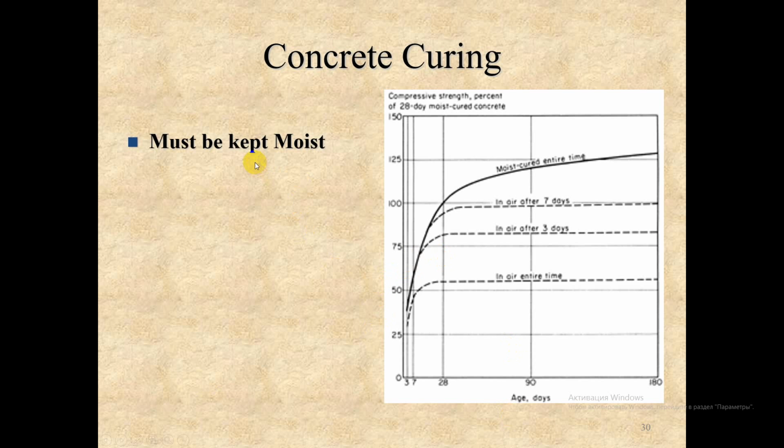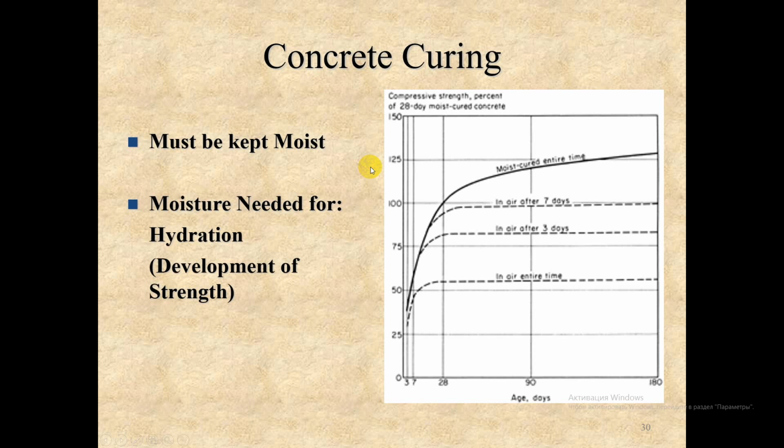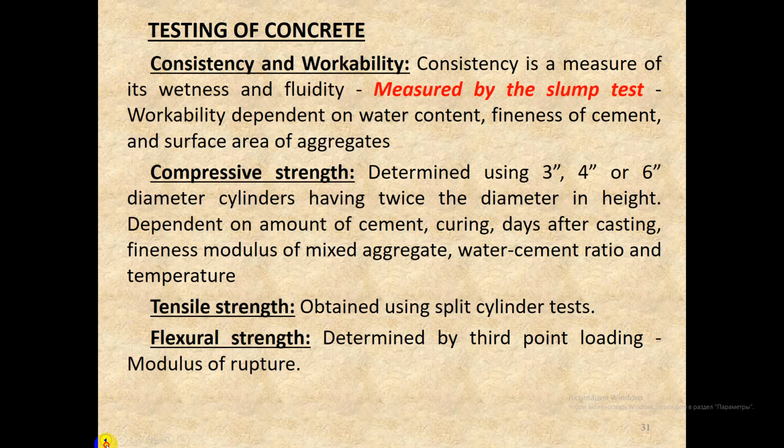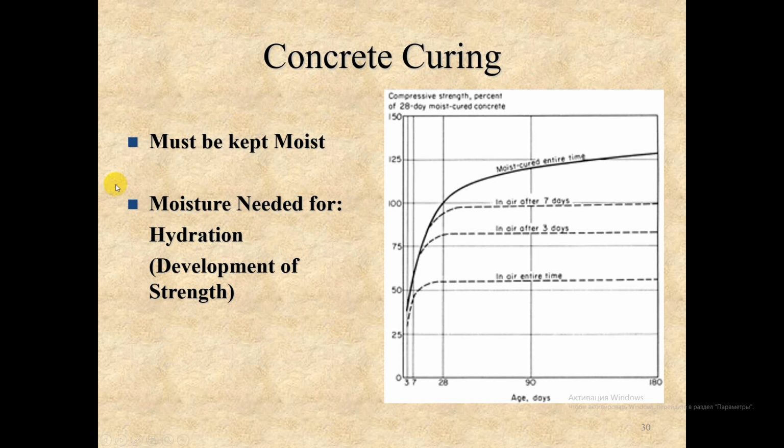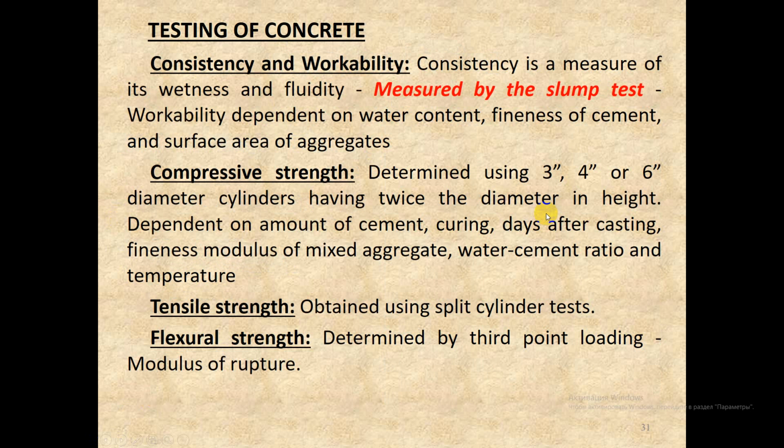So concrete during curing must be kept moist. Moisture is needed for hydration and development of strength. Testing of concrete: consistency and workability.